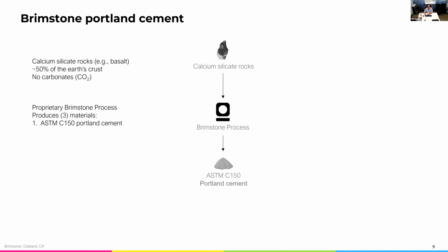As part of our process, we actually will produce a silica residue. Pozzolanic materials, or SCMs, have pozzolanic properties which let them react with certain compounds in a concrete system and allow the concrete to gain strength. SCMs are really good because they can increase durability, they can increase strength over the long term. They can obviously reduce CO2 from the cement by substitution.